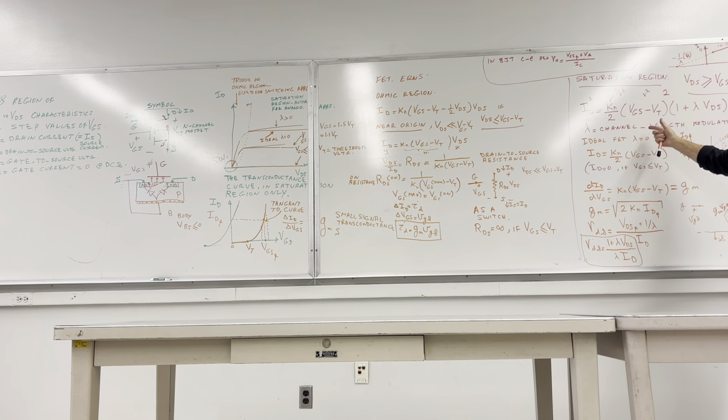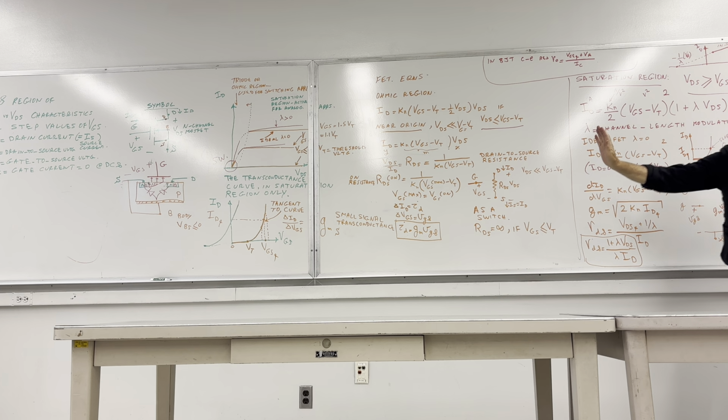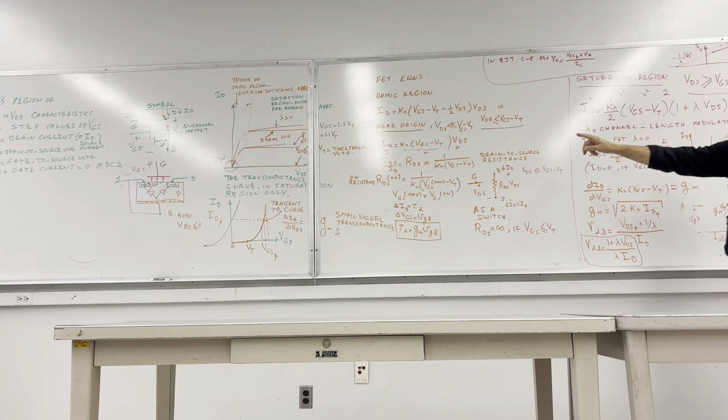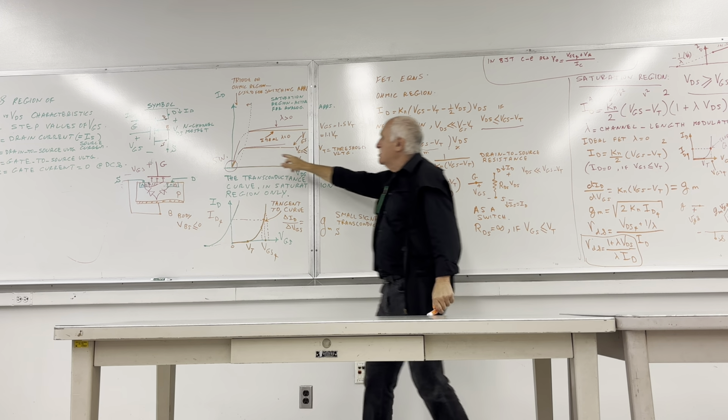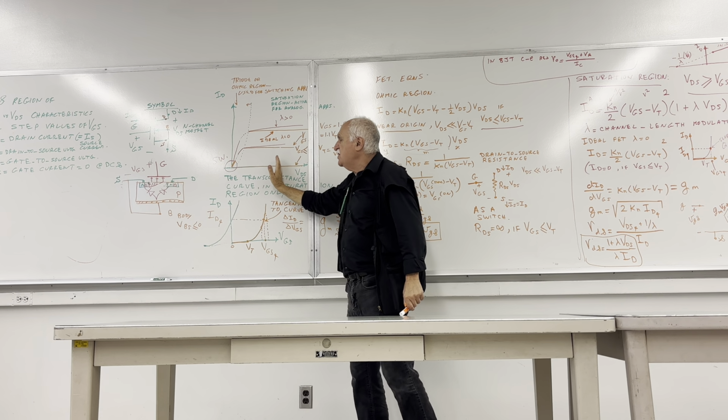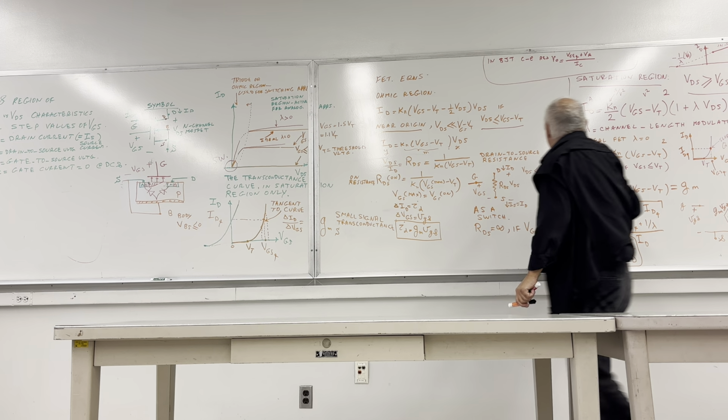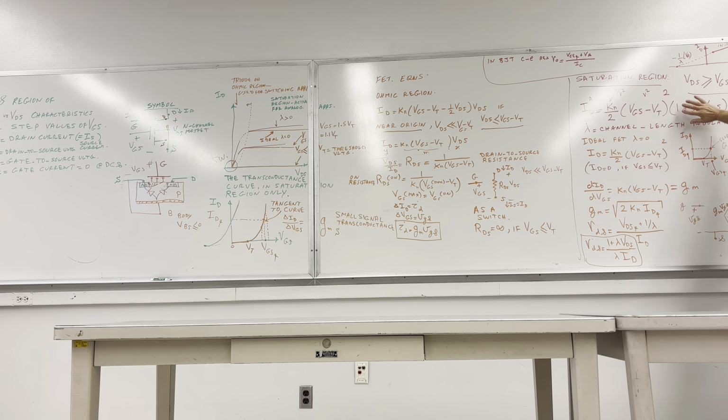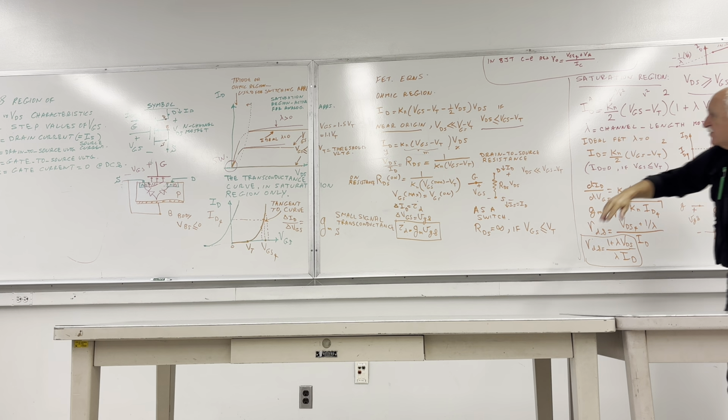Then the saturation region. So once we pass to that side, ideally, if we assume the channel does not retreat, doesn't shorten because of the drain to source voltage, and the lines are constant, independent of the VDS, then this equation would be adequate without that to calculate VGS against the ID, which is nothing but the transconductance curve.